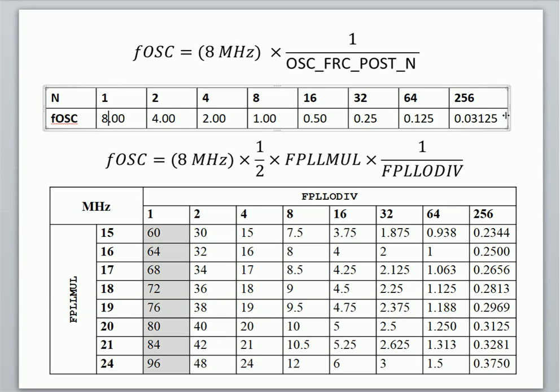So a big range in speeds for the chip. Why would that be good? Well, it depends what you're operating at. The faster a chip operates, the more power it consumes. If you want to take this chip and attach it to a battery and leave it for a while, you don't want your batteries to die out. Maybe you don't need to be operating at such high frequency.